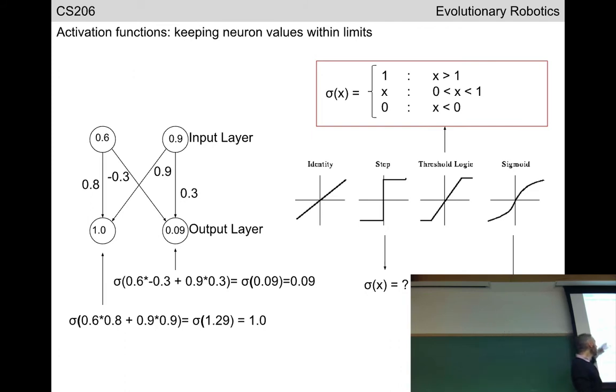And what an activation function does is take as input the raw sum and pass it through a certain function that will squash the raw sum down to lie within some predetermined range. In the work we're going to be doing here, we're going to arbitrarily set the predefined range to be between -1 and +1. So for all of the neurons in your simulated robots, we're always going to know what range they lie within, between -1 and +1.